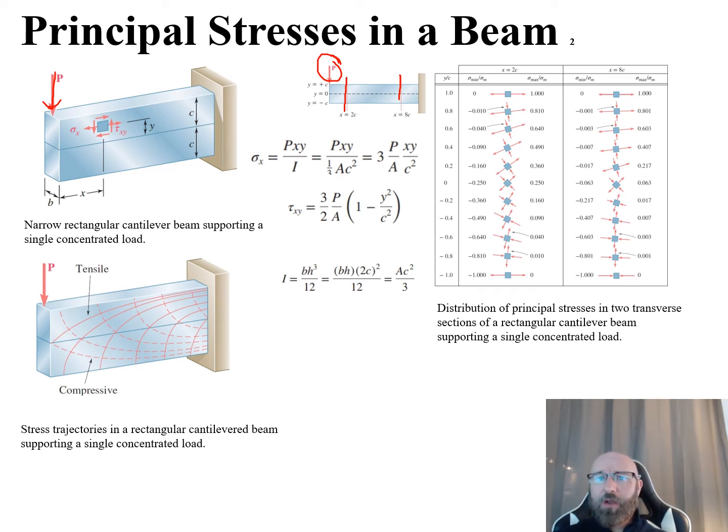But a thing we want to note here is that as we get closer to this end where our load P is, Saint-Venant's principle no longer applies as we get close to the end of this load, where our P is at the end of the beam right there. And therefore, our equations 8.3 and 8.4 from our textbook, so these equations here, cease to be valid.